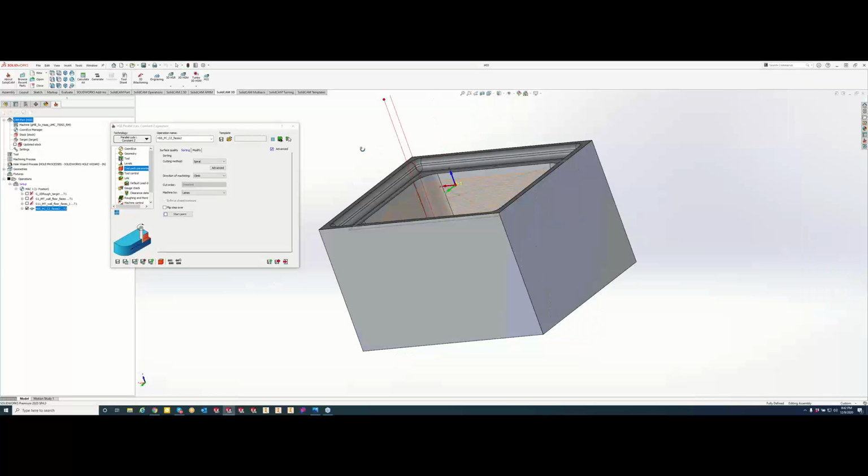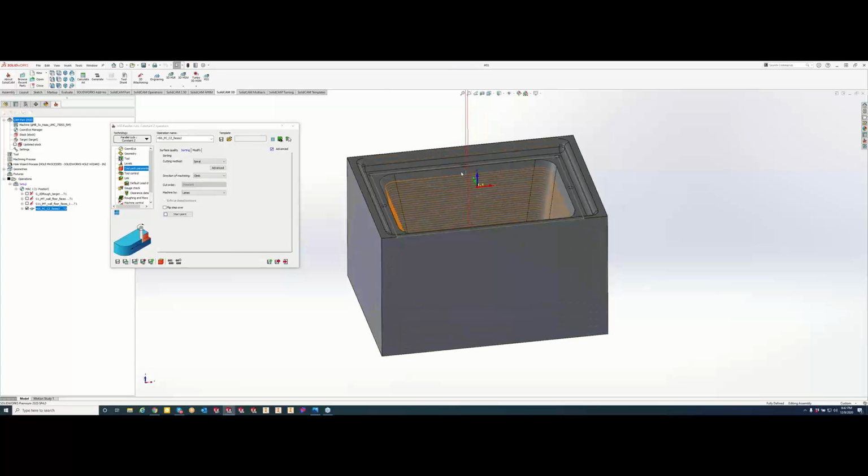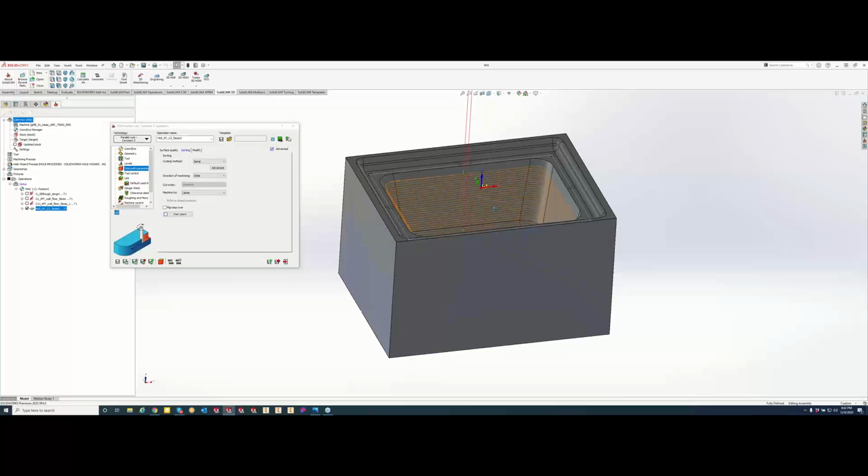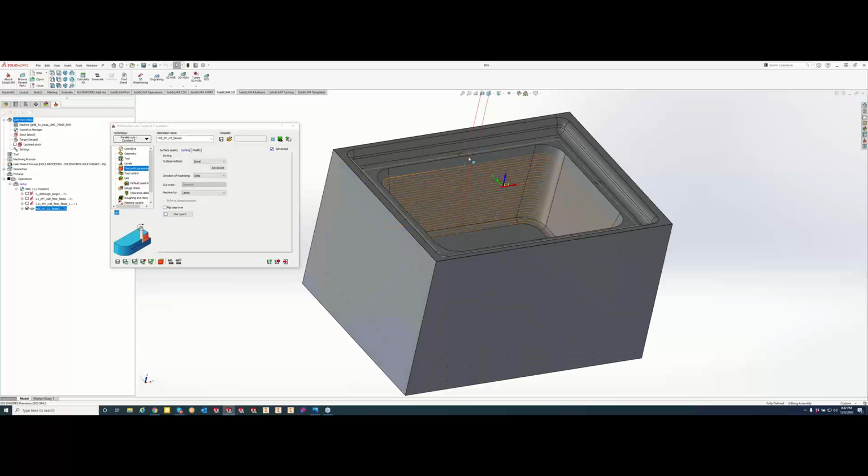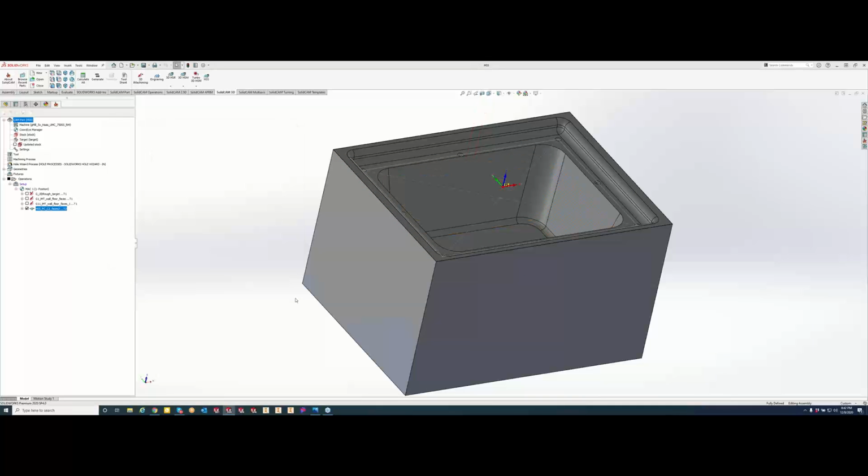Now we are doing a nice spiral cut, doing one entry and one exit. So I get a little side view here, doing our laps all the way around in a corkscrew pattern. So I really like the way that looks. I don't have to worry about any links at this point because I don't have any gaps. We're in a constant surface all the way around. Let's go ahead and see what this is going to look like in Solid Verify.